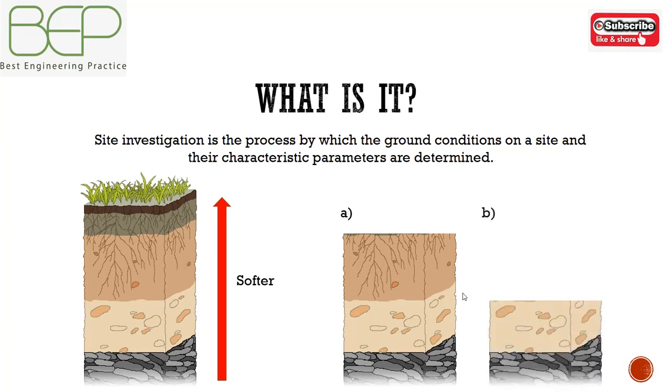In the other case, he might excavate the soil adjacent to the structure and replace it after construction. Then compaction methods will largely control the final pressure. In this case, the data on the local ground condition will have little value when calculating the earth pressure to be supported by the wall.